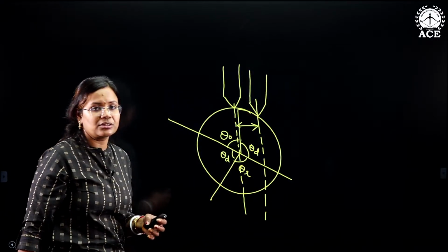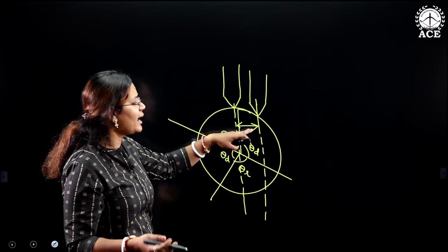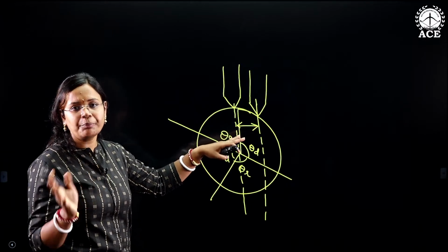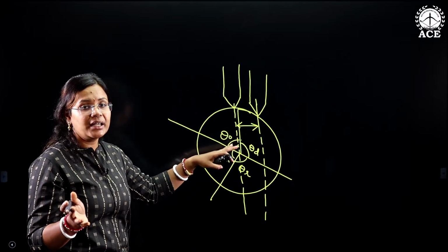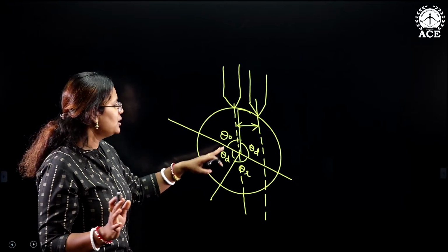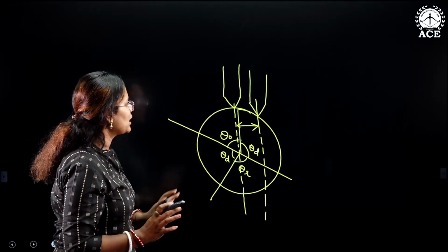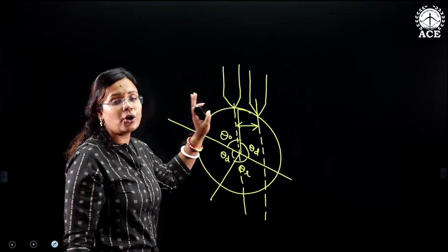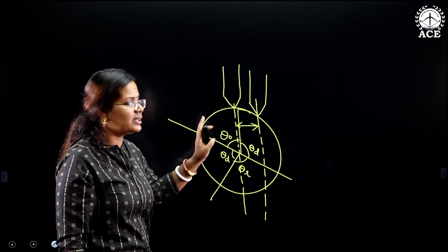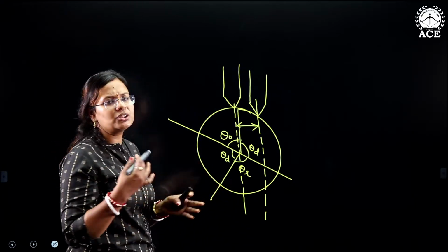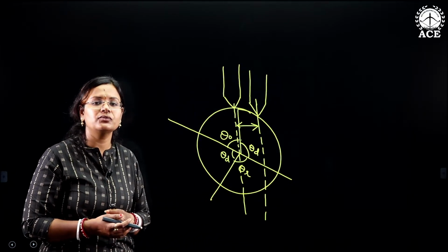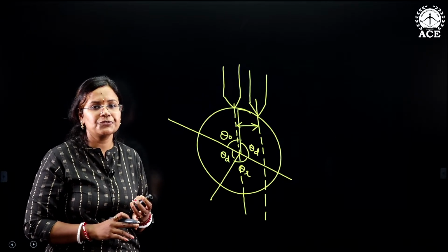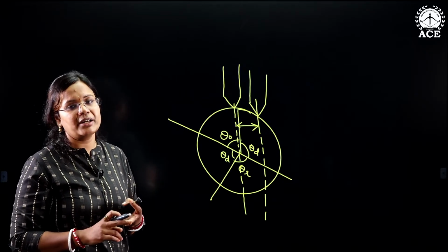That is another condition. So the second condition says that the axis of the follower does not pass through the axis of the cam, but it is at a certain offset from the center of the cam. So this is how you should draw your knife edge follower. Drawing the follower is a must, it is very, very important. They may also mention different kinds of followers, as we have 3 different types: knife edge follower, roller follower and flat faced follower.